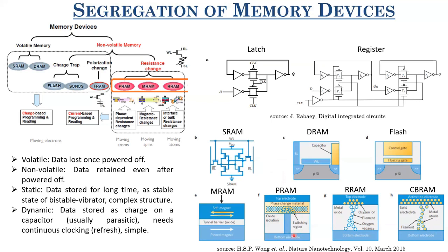And when you melt this with the help of Joule heating, if you quench it fast, that is, if the duration of the pulse is very short, then this material doesn't get enough time to grow into the crystalline state. So it remains amorphous.